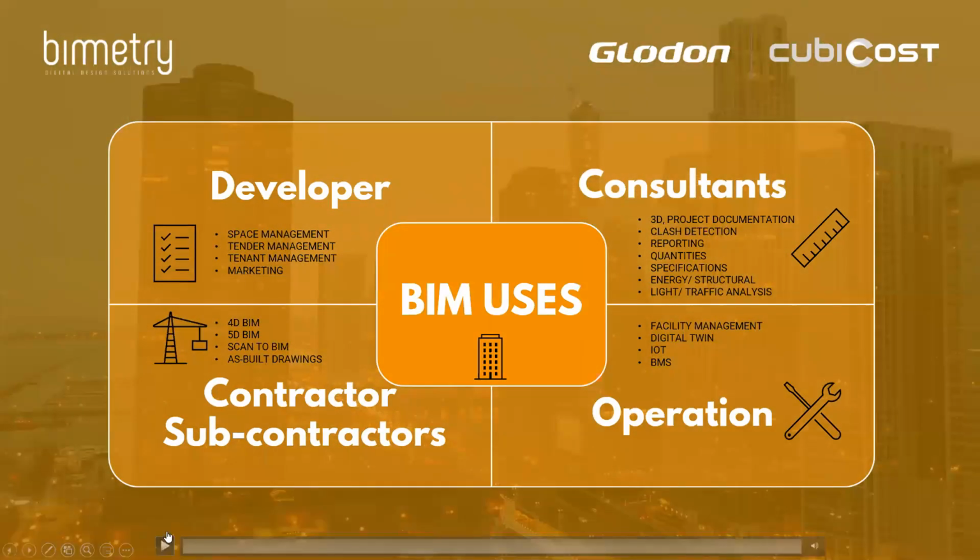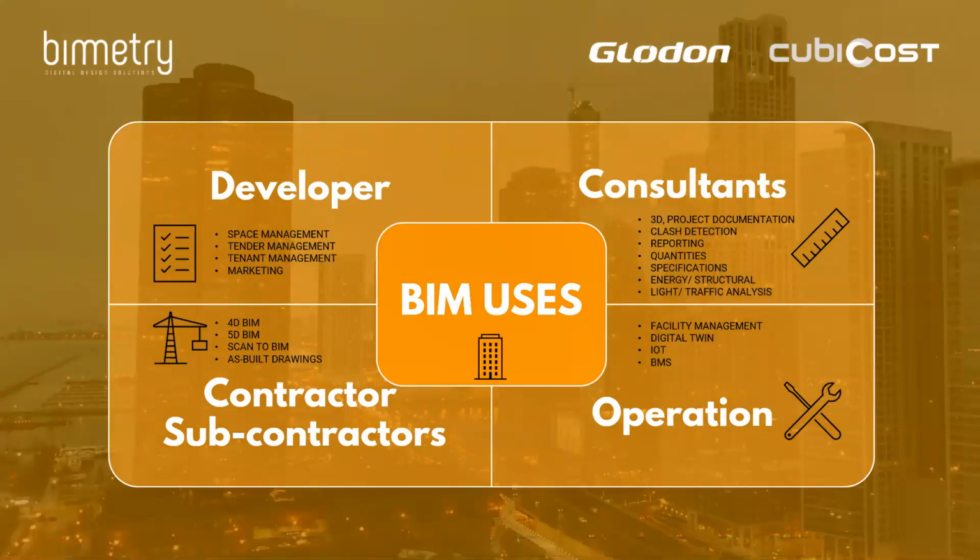As we mentioned before, the keyword in BIM is information. The BIM authoring tools make a difference between the object categories, and we can extract structured data in spreadsheet format. For example, we can extract all the quantities and price details if we have inserted the cost. As QS and cost estimators, this information might be very valuable. Even if it's not always complete or 100% accurate, this can speed up your work a lot.